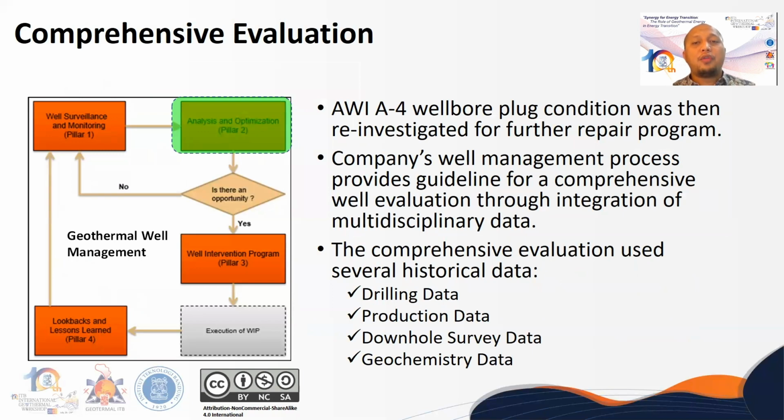The AWI-4 wellbore plug condition was then reinvestigated for the further repair program in order to prevent a similar failure from the 2015 operation. We used the company's well management process, which provides a guideline to do the comprehensive well evaluation through integration of multidisciplinary data. This comprehensive evaluation uses several data such as drilling data, production, downhole survey, and also the geochemistry data.